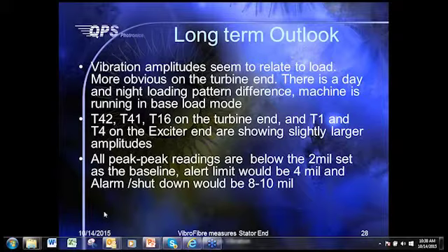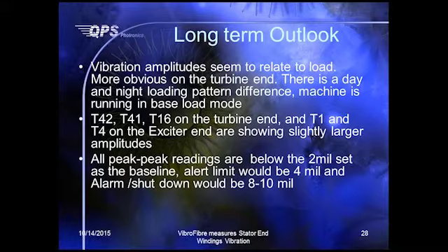If you have the ability to determine whether the structures are loose or not, you can have a much less expensive way of making it better. For example, you can re-wedge it and improve the blocking and the support, to minimize the damage done by this vibration.